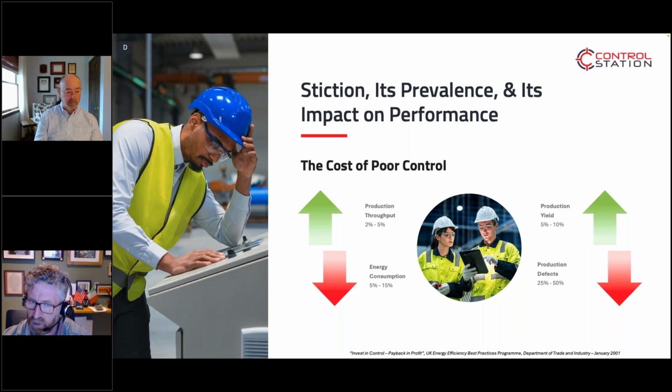Oscillation is average absolute error increase. Oscillation is moving away from set point. Oscillation is variation in where you want to have stable control. And it's going to feed into all of those actions there to start to bring variability into it. Throughput: if you can't reach set point quickly, you're going to reduce your throughput.